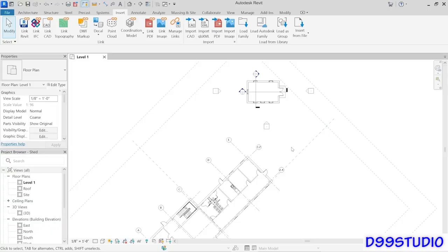Now, one last thing I want to point out to you is if you are setting up a shared coordinate system with a model that has geo-referenced coordinates, those coordinates will come across in Revit. So there's an example of that in the out-of-the-box Revit sample model. Now, we've opened up the sample model previously here in this course. I welcome you to open it up directly and see this for yourself.